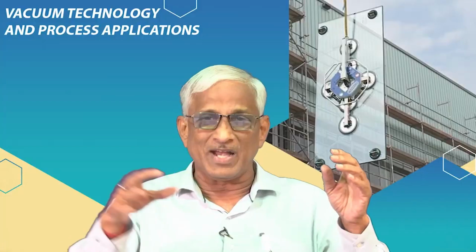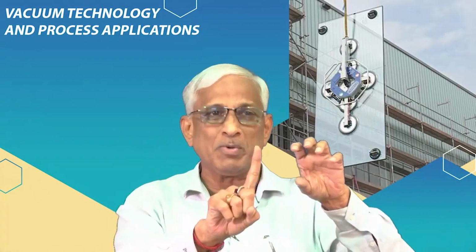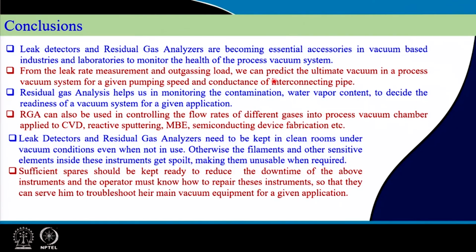Once you know the leak rate and the pumping speed, the ultimate vacuum can be easily worked out using the standard law: Q dot total is pumping speed into equilibrium pressure, and that equilibrium pressure will be the ultimate vacuum. If it is not acceptable, solve the leak; such decisions can be taken. Or it may be a degassing problem, then RGA will tell it is not a leak. So, by connecting both these instruments, you can nicely understand the trouble also.